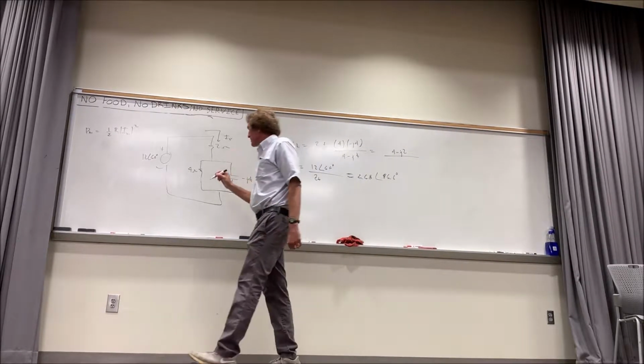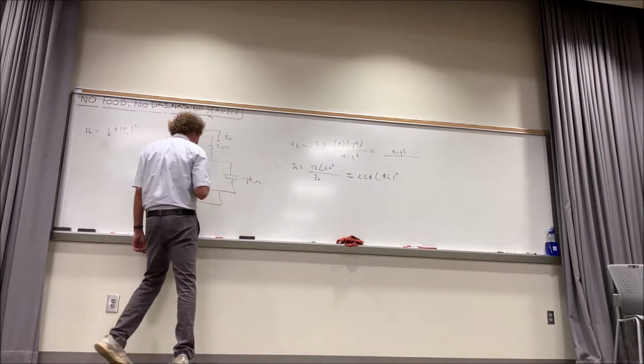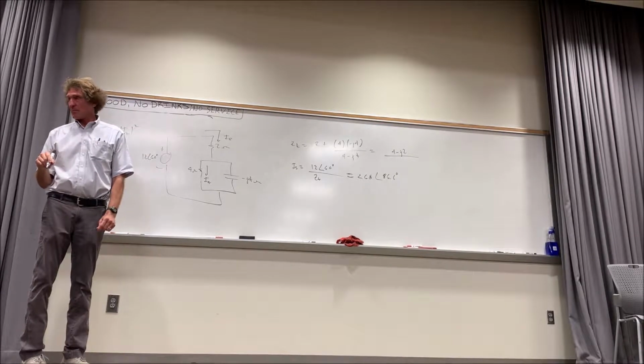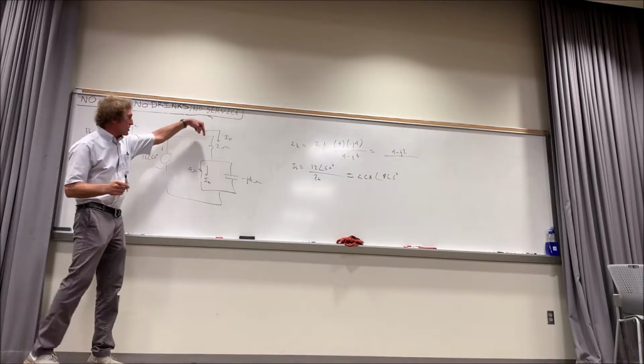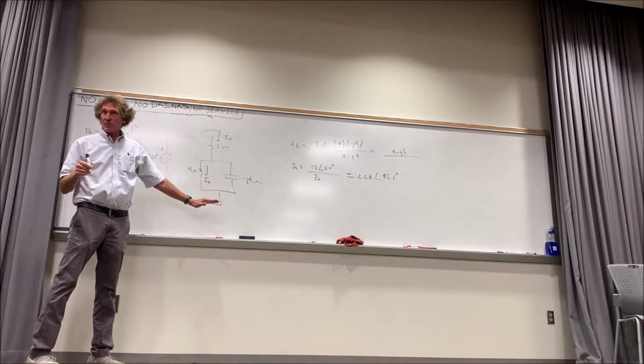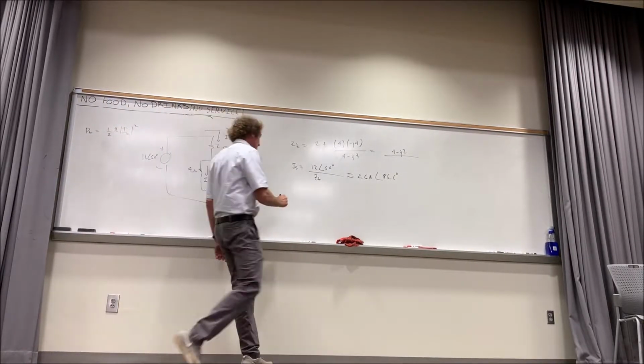But we need the current through this 4 ohm right here. That's what I need, I4. So how am I going to get that? How would you get it? Anyone? This is a standard kind of problem. You've got the total current flowing into the parallel combination of 2 elements. How do we always get this? This is current division, don't we? So what does current division say?